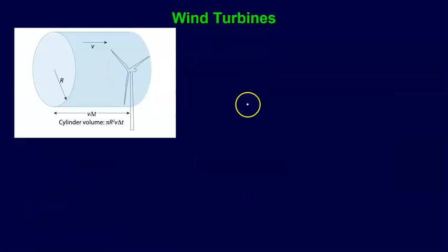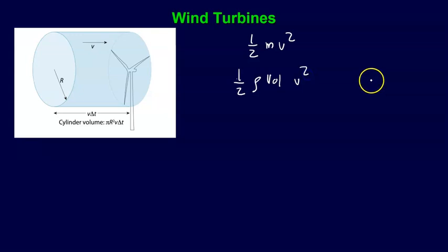So now to try to figure out how much energy we get from one of these turbines, let's just use our equation. Our equation is kinetic energy. That's the energy we get from energy of motion. And because it's hard to say what piece of wind we're talking about, we'll use density times the volume. I'll write out volume because there's also a velocity squared term. So here is the energy we'd be talking about: 1/2 rho times the volume times v squared.